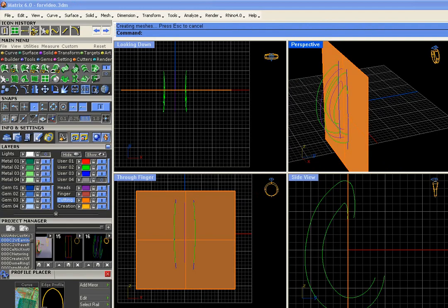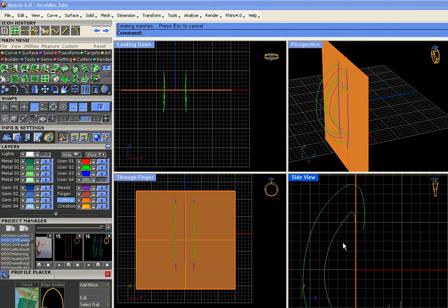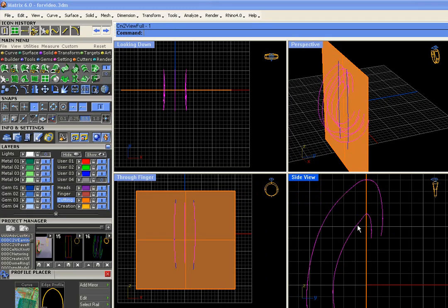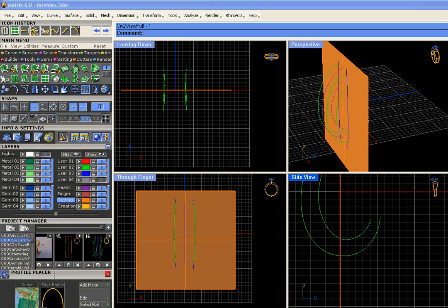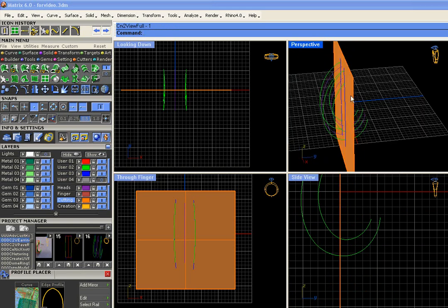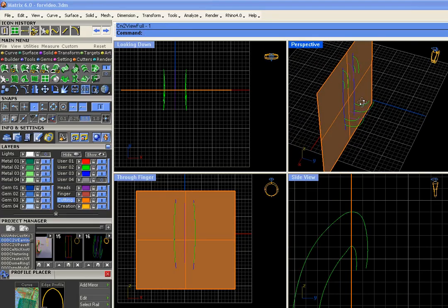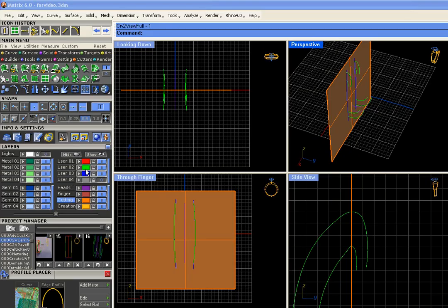Okay. And looking at this, I want to take everything green and purple, just slide it back a little ways. I'm cheating, but that's okay. Okay. And I'm going to set up to draw a profile that touches all 4 of these rails. I'm going to do that by running the green with the orange and running the intersect command. It lives right here. And that places points wherever curves and surfaces interact.